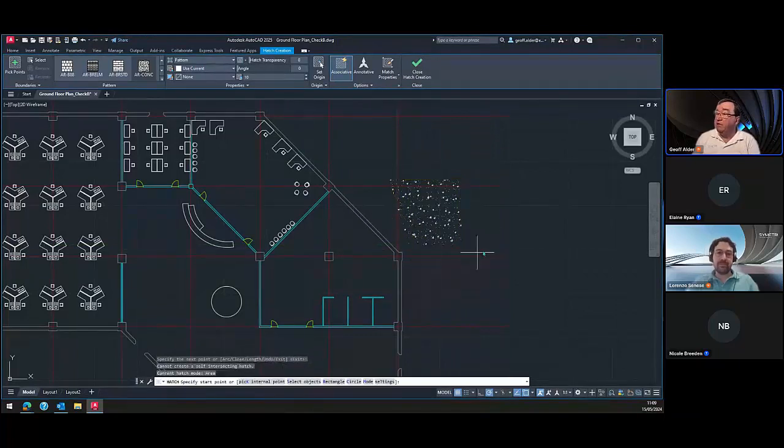So instead of actually creating a polyline and then using a boundary projection to do this, I can actually place that on there. So I find this quite useful. If I want to put a hatch pattern across several components, I can just tap round the component to highlight where the hatch is going to be, because if I need to do it as a select internal point, I need to select islands or decrease islands and stuff like this. So I quite liked that.